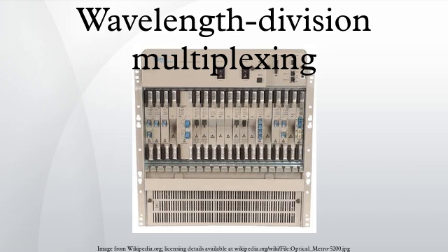An interesting and relatively recent development relating to coarse WDM is the creation of GBIC and small form factor pluggable transceivers utilizing standardized CWDM wavelengths. GBIC and SFP optics allow for something very close to a seamless upgrade in even legacy systems that support SFP interfaces. Thus, a legacy switch system can be easily converted to allow wavelength multiplex transport over a fiber simply by judicious choice of transceiver wavelengths, combined with an inexpensive passive optical multiplexing device.